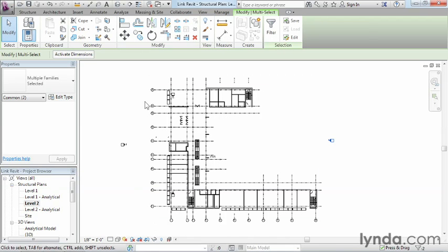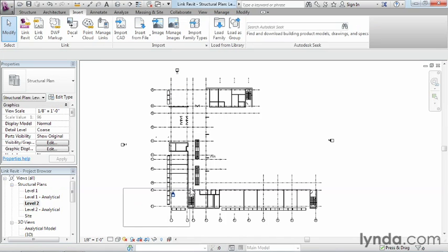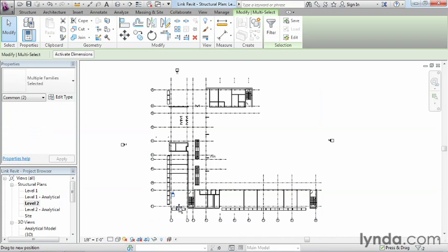in our elevation. And we'll need to do the same thing with our north elevation tag by just windowing around it, clicking and then dragging it to the outside, and doing the same thing here with this elevation tag and just clicking and dragging it to the outside. So now we'll be able to see from essentially right about here over in this direction and be able to see the whole building if we would go to an elevation view.